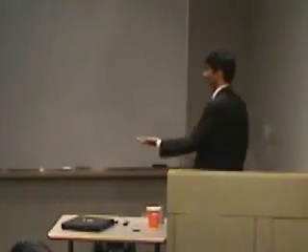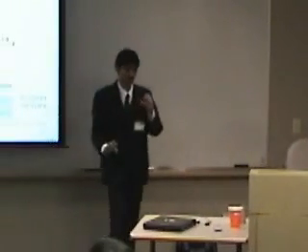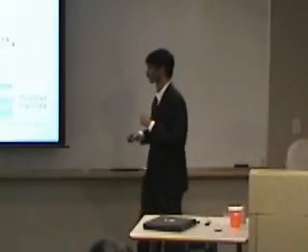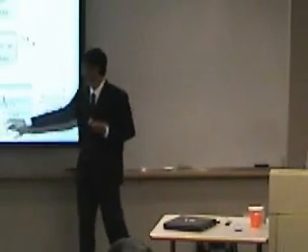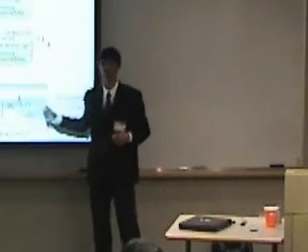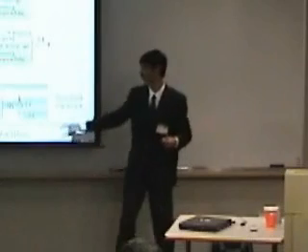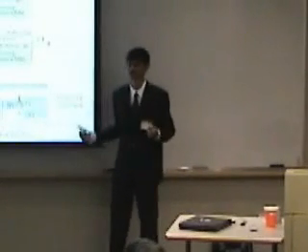So now let's say this is the simplified hardware we have, and there are 4 processing cores in the system on the hardware. Each processing core has some local memory, and each processing core can communicate with its next neighbor using a next neighbor channel. This is the message passing communication channel, which is the fastest implementation for communicating packets.